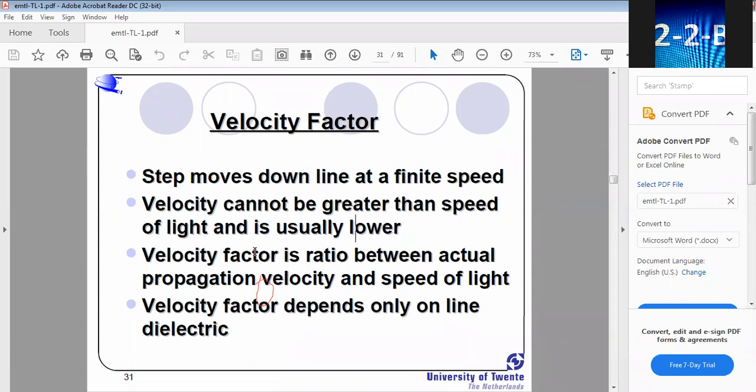But factor means how much quantity existed. For the half-wave rectifier, how much AC content exists in the rectified output? 1.21, or simply 121% of AC is present in the rectified output, more than the input. For the full-wave rectifier, it is 48% of AC. Ripple means AC content present in the rectified output, but how much quantity is the factor.